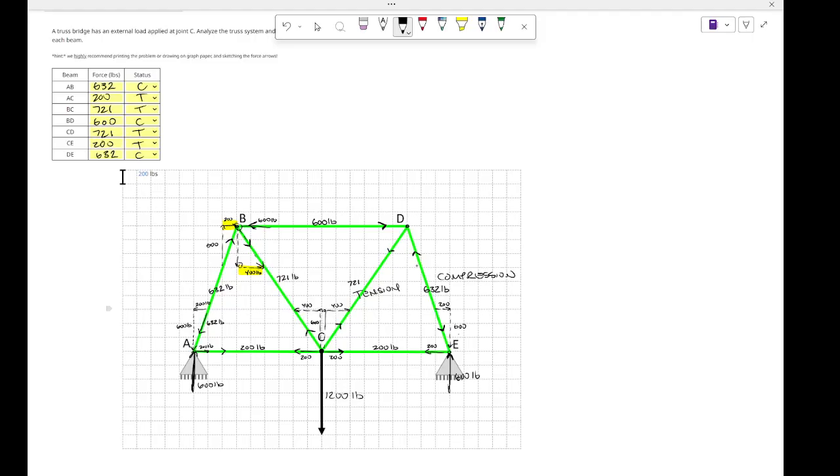So you're going to be looking at what the materials are made of, how thick they are, how much they can handle in compression and tension, and determine where your weak points are going to be, and then engineer around trying to make sure that structure is strong enough to support whatever loads you're going to handle. But here's a little simple breakdown of a nice symmetrical truss that walks you through how we can break down each individual point and look at the forces at that point alone and evaluate what forces must be in those beams.